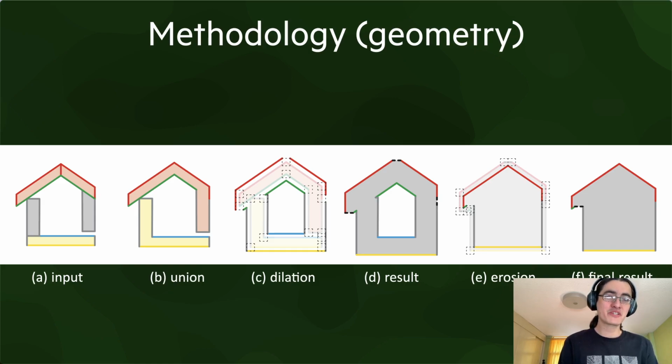In terms of geometry, you need to do a few things for this, because BIM models are in practice used only for visualization. So people don't care if the geometries don't match perfectly. You end up with small gaps and small overlaps within the elements, which means that when you try to compute a volume, like you have done in the voxelization assignment, you are not able to compute an interior volume because the volume is not really closed.